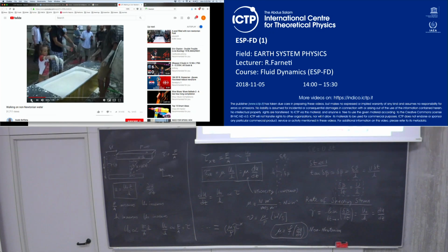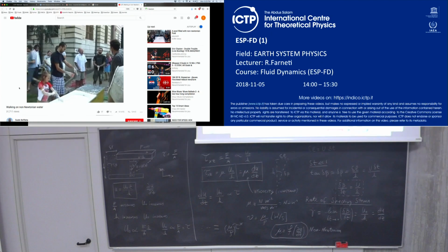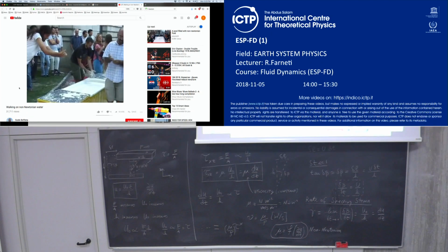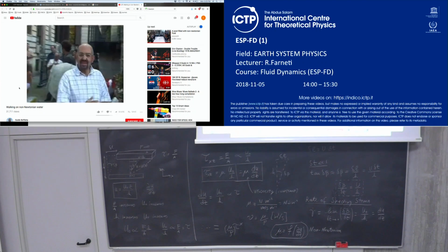Okay? Cornstarch, as you see from that little girl, is a non-Newtonian fluid. Okay? It's a fluid. You see that the fluid is dripping from the girl's hands. Okay? And that bathtub is filled with cornstarch. Now, the more shear stress that you apply to cornstarch, the more viscous it becomes until becoming close to a solid. This is a nice demonstration of shear thickening non-Newtonian fluids.